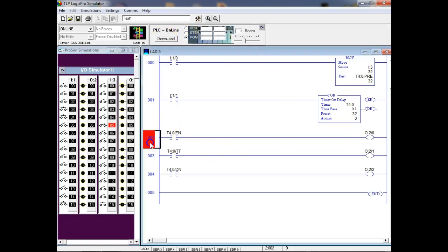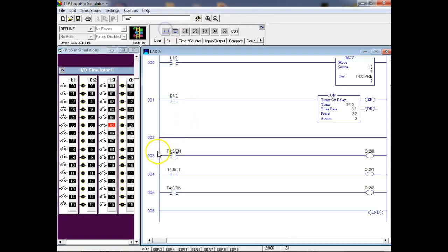If I come up here for some reason, well, we will start off. I'll use the same switch, so we can use the same input multiple times, right? And it's no error. This is where it's good to assign symbols. We don't do that in RSLogix. So we'll come up here and we'll put in a retentive timer.